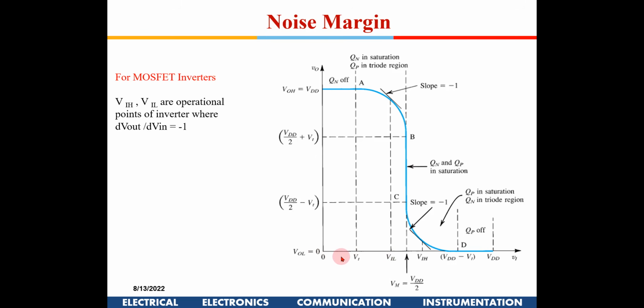So it doesn't matter, like you don't have noise coming off that order. Now we are speaking about 7 nanometer, I guess the power supply voltage is less than 1, around 0.8 volt or something. Now you can imagine the entire curve has shrunk, both in the y and the x axis, and you just have close to 0.3, 0.4 volt as the noise margins. Okay, so those are the issues which come up in modern day circuits.